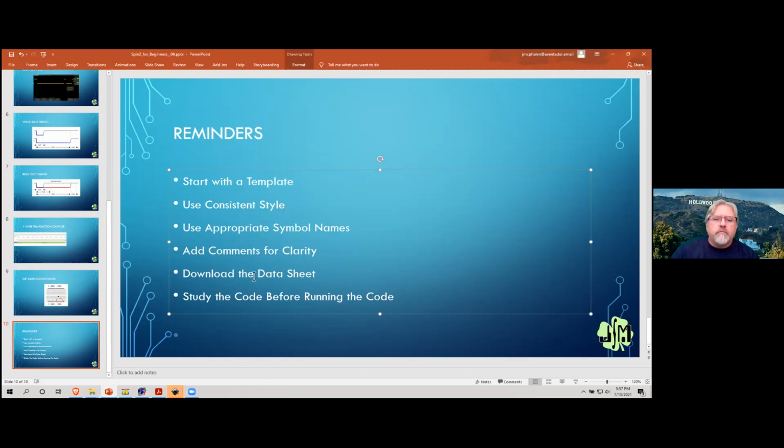And again, as I said, I'm going backward now, download the data sheet. If you get a new part, the first thing you should do is download the data sheet, because you have to have that reference. There was a gentleman who got my phone number and called me very angry because my one-wire object doesn't say that you have to put a pull-up on the line. It's in the data sheet. And maybe this is a flaw in me, but I don't rewrite the whole data sheet into my code. The idea is we are involved, even as hobbyists, to a degree in some level of engineering, and we have to take responsibility to do that.